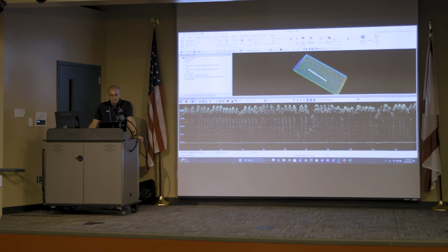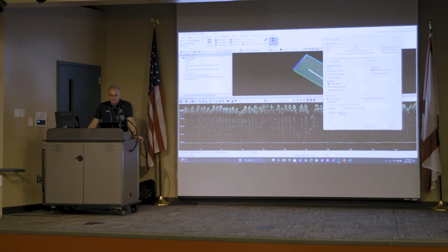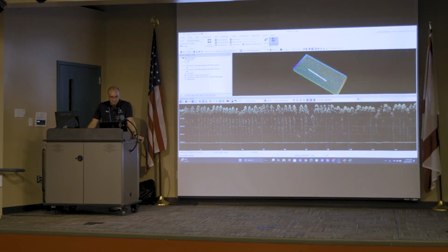So this is basically the numbers that have been used for this kind of forestry. The first number is basically the crown diameter. So we actually need three data points from the data set. The first one is this average crown diameter. I can check that just using the profile window and the measurement tool, and check here the space between the crowns of the trees that we have. With this information, I basically put it here in the algorithm like this. The second one is the tree distance.